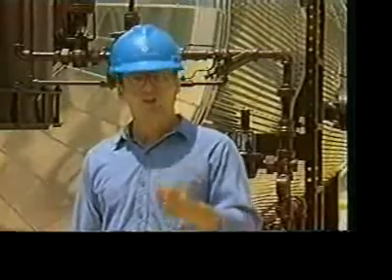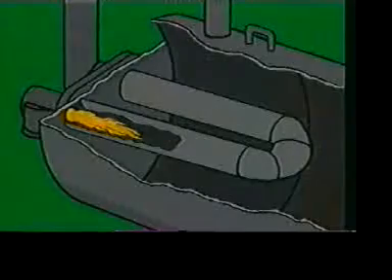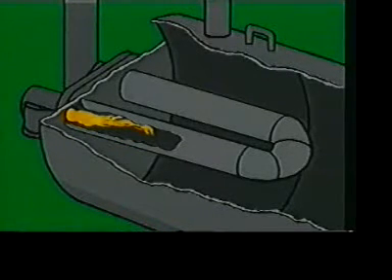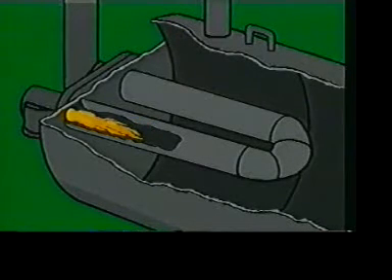Most emulsions contain a certain amount of sludge and solids, so fire tubes should be checked periodically for corrosion, rust, and accumulation of scale. The burner flame should aim straight down the center of the fire tube. If the flame hits the fire tube directly, a hot spot will form, and the fire tube could fail prematurely. It's best for the burner to come on and burn steadily for a long period of time, rather than blasting on and off. The best flame is yellow, with just enough air to keep soot from forming.